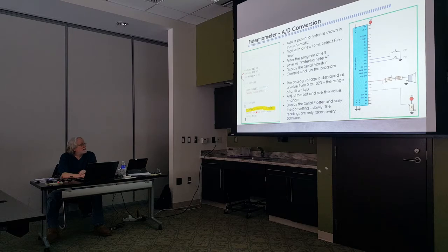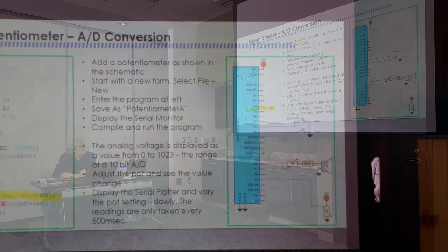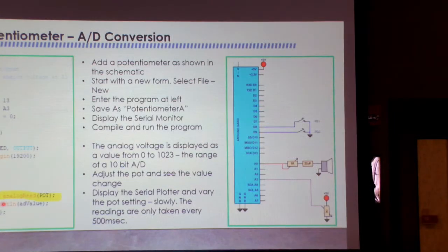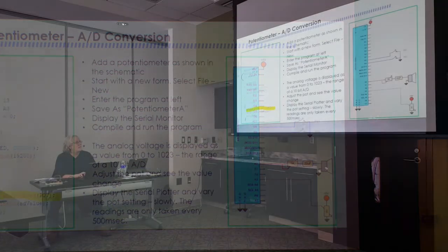Here you see the int AD value, and there's no other routine, so it's really not that useful, but the scope of that variable would be open to any routine I put in that file below it. If I had a subroutine down here, it would know what AD value was. And if I had a subroutine below that, it would know what AD value was.